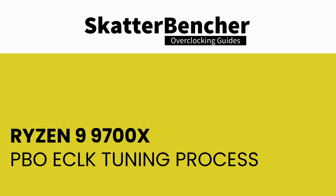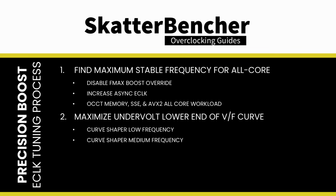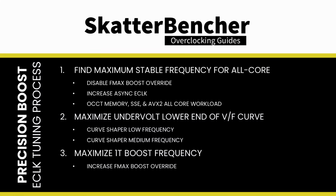The manual tuning process using eCLK can become quite convoluted because it spans the entire range of workloads, from light single-threaded workloads all the way to heavy all-core workloads. My eCLK tuning process for this Ryzen 7 9700X was as follows. First, I tried to find the maximum stable frequency in all-core workloads. Second, I tried to undervolt the lower end of the VF curve as much as possible. And then third, I tried to increase the maximum frequency in the 1T workloads.